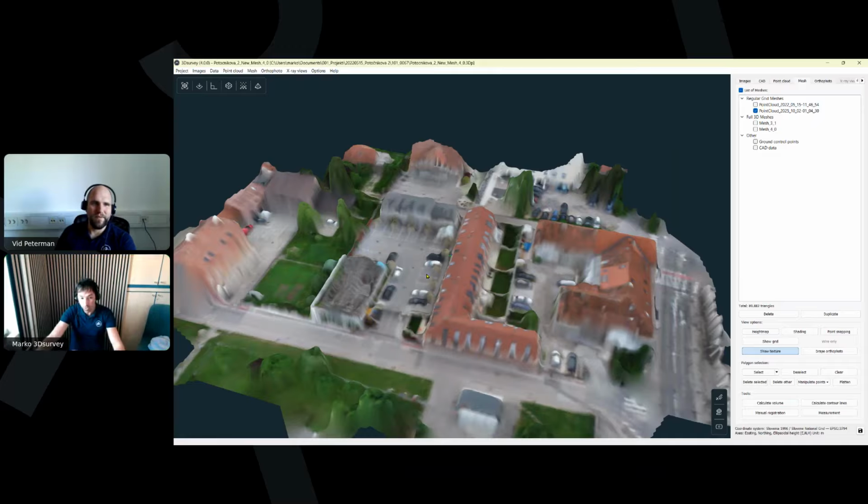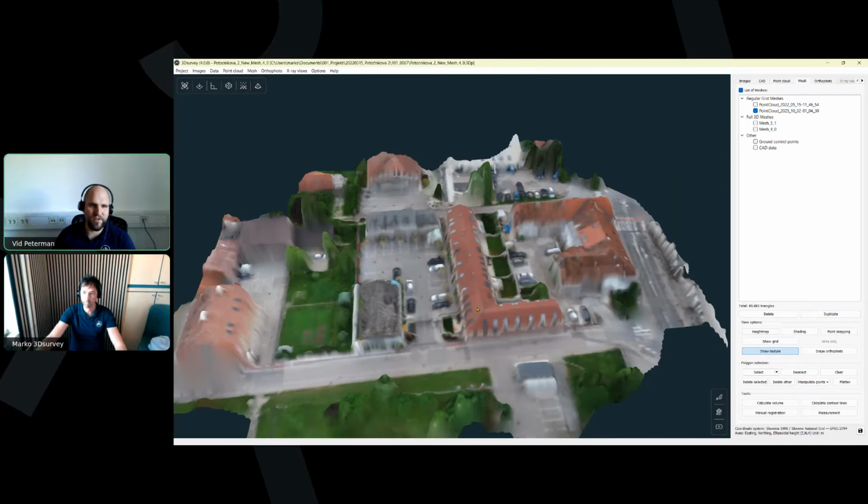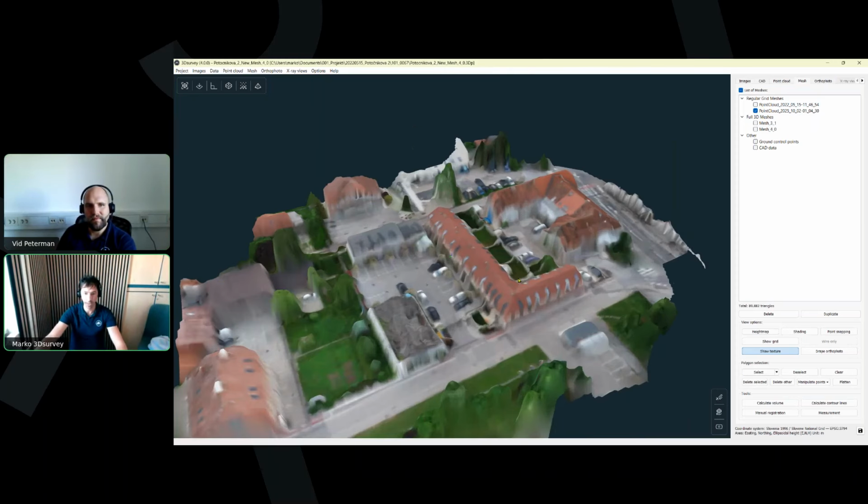Or of course, if you do the coverage of traditional orthophoto calculation, or if you need contour lines and all this stuff. Exactly. For these things, we still use the old regular grid mesh where we define the grid cell size, and this one is also the most accurate one to use with volume calculations. Okay, thank you, Vit. I did not forget to mention this one.